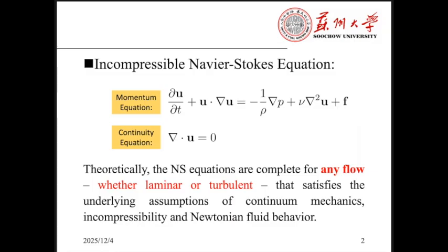Here is the incompressible Navier-Stokes equation. And we all know that theoretically the NS equations are complete for any flow, whether laminar or turbulent, only if the flow satisfies the underlying assumptions of continuum mechanics, incompressibility, and Newtonian fluid behavior.